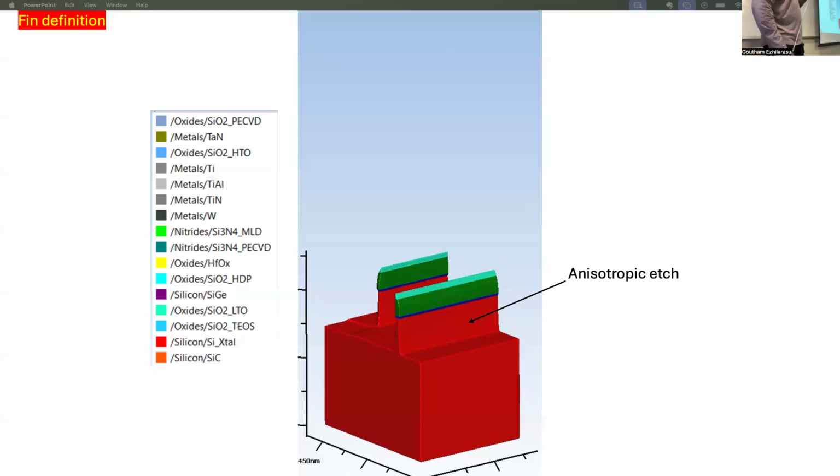So in this example, from one mandrel, you make both the NFET and PFET. When we make our layout, we use two mandrels, so it'll be different from this. This is just a demonstration of how the process works, but obviously in your case it'll be different.